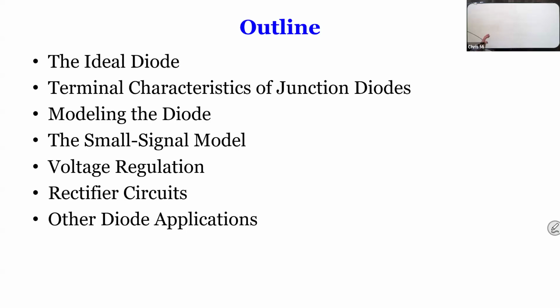Now you dope some impurity, boron or phosphorus. Once you dope it in, it's going to bond with the silicon, but the bond leaves either an extra electron or an extra hole. So if you dope in a lot of impurity atoms, it creates either a lot of electrons or a lot of holes.